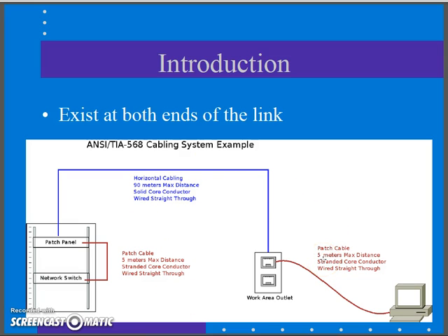So just a super quick review. Back in Chapter 5, we talked about cabling, so we pulled the horizontal cabling in the lab. In Chapter 6, we talked work area outlets, so we turned right around and terminated the outlet jack here. In Chapters 7 and 8, we talked about terminations in the closet and patch panels, so we terminated our patch panel here in the lab. Now at Chapter 9, we're looking at patch cables that we would use here in the closet to go from patch panel to switch, as well as patch cable out here at the work area to go from the work area outlet out to your user computer. So we're looking at the patch cables on each end of our horizontal cabling, if you will. That's the part we're looking at now.